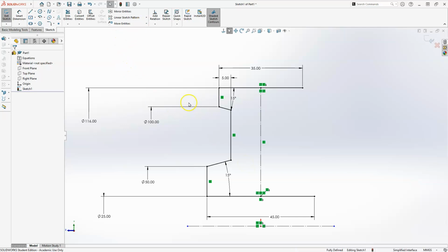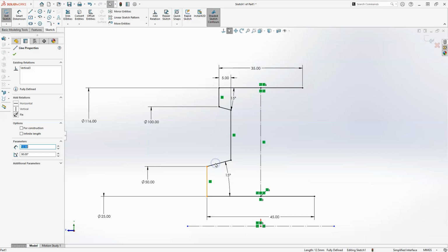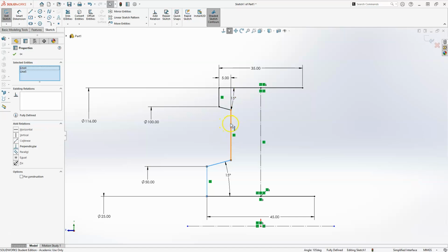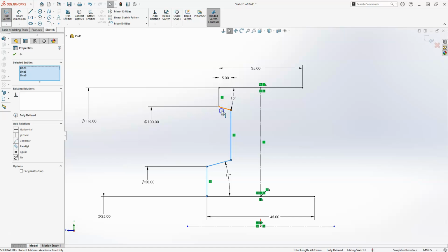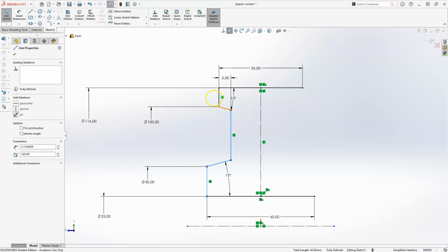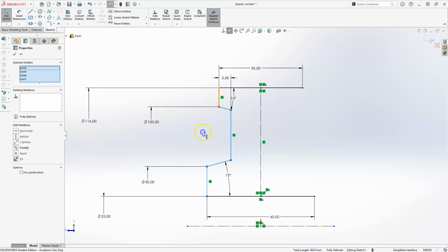Now, I don't think we've had an example where we use the mirror command in the sketch. If I did, I do apologize, but it should be really simple. We're going to select all of these components, right? And don't forget to hold down the shift button as you keep selecting each of the lines. Okay, I got one more line to select. Okay, so you can see my list there running.